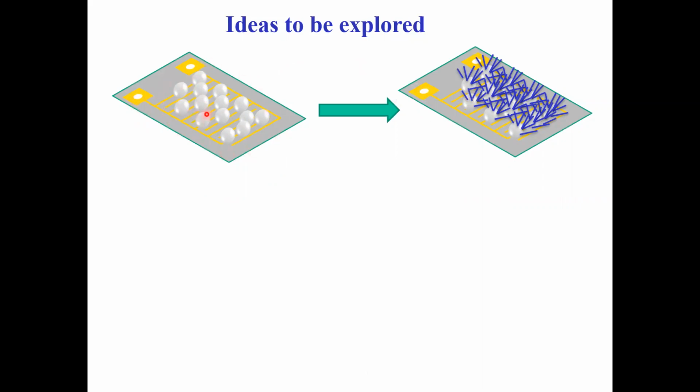So the idea is that first you spread titanium alloy particles on the sensing platform, alumina substrate with interdigitated gold electrode printed on it, and do the argon treatment where you grow this TiO2 nanofiber, and then basically do the sensing on this kind of nanostructured platform.